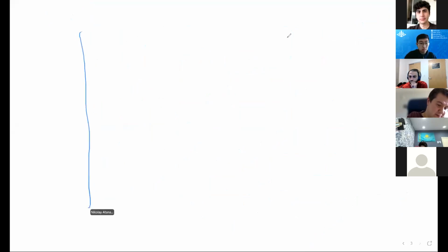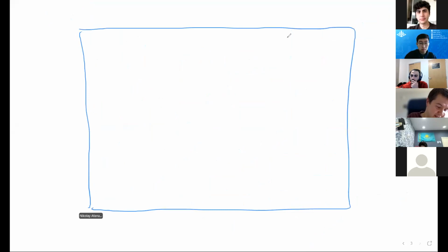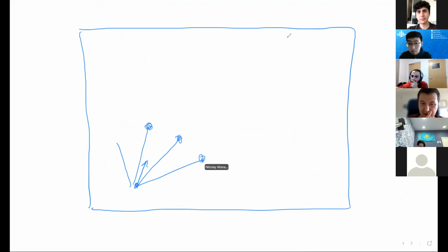In the first demo, we did something like this. We had the robot with the orientation. It was shooting the LiDAR beams. And then wherever we hit the point, we just found its coordinates in the global frame. So we had this R, and this angle alpha over here, and we knew the robot orientation theta and the X and Y position of the robot.